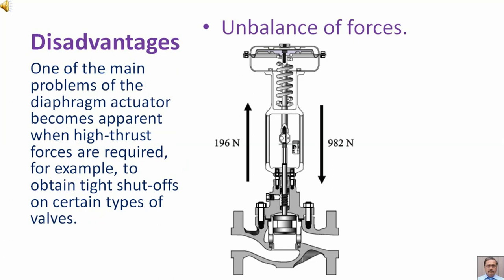Disadvantages: one of the main problems of the diaphragm actuator becomes apparent when high thrust forces are required. For example, to obtain tight shut-offs on certain types of valves.